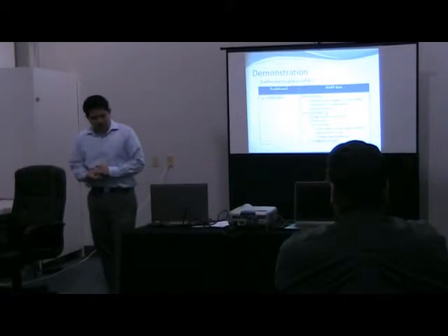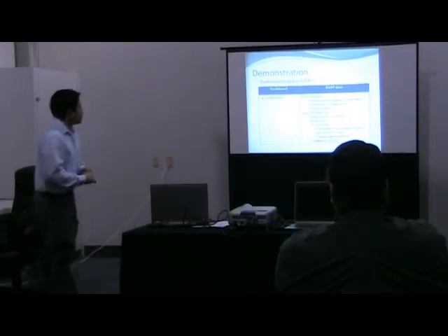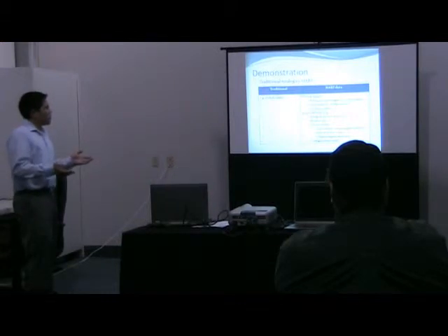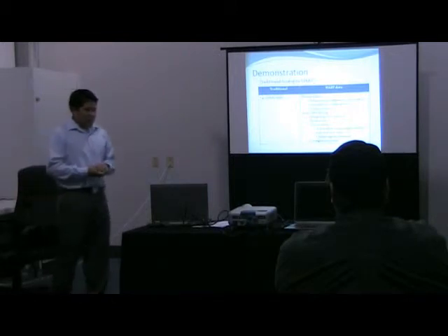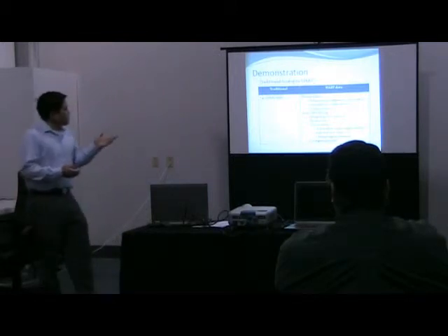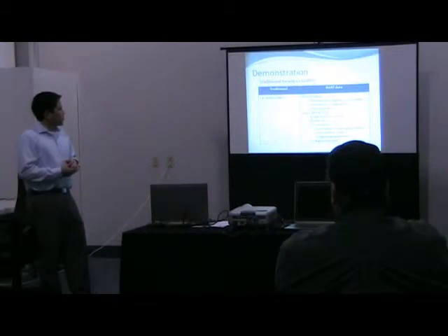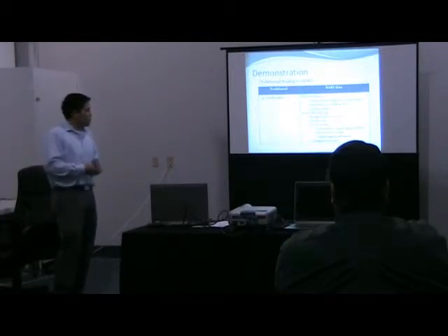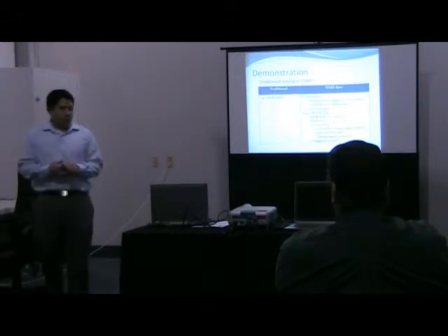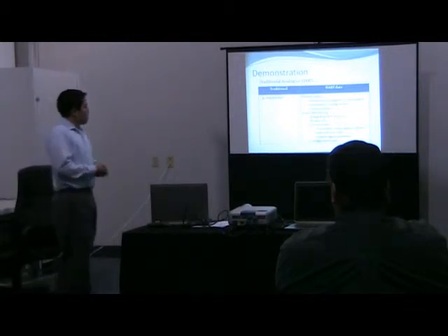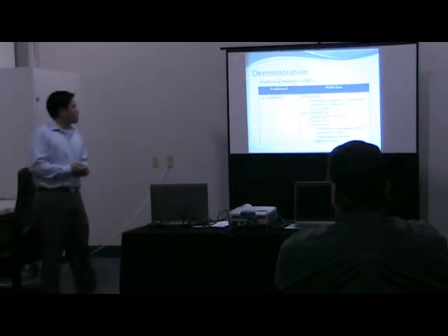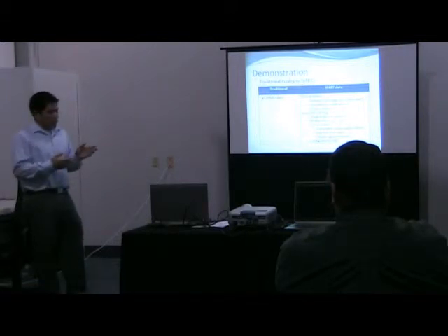So here's a table showing your traditional analog wiring versus your HART data. Traditionally, all you have is your 4 to 20 milliamp signal. Some of the information that you pull from HART includes process values, such as your primary value, which is basically the digital version of your 4 to 20 milliamp. Secondary, if you have an ultrasonic sensor that has a temperature sensor as well, you can obtain that data, and tertiary values. In terms of sensor monitoring, it can give you range and process alarms.